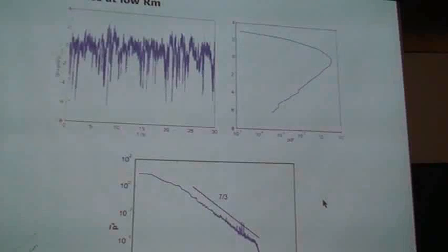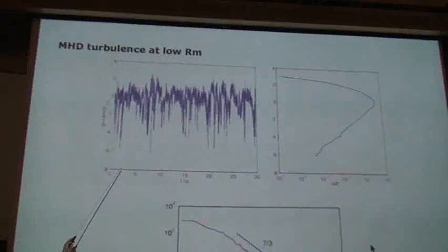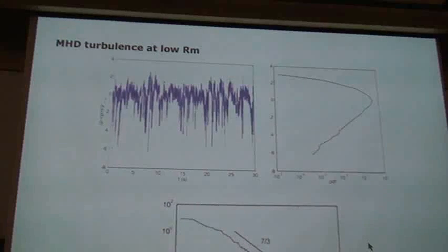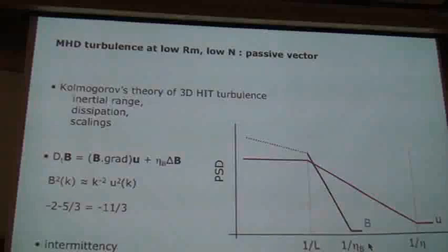So, these are conventional measurements for turbulence. Kolmogorov turbulence inside the flow. What you see here is a recording of a pressure probe at the flow wall. So this is in time what pressure you see on a probe at the wall, and this minus 7/3 spectrum is characteristic of fully developed Kolmogorov-like turbulence, as we will see in a minute. So the proper framework for this developed flow is Kolmogorov theory.